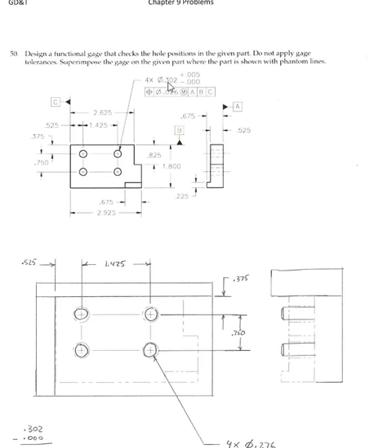So we've got 4 times 0.302 plus 5 minus nothing. Therefore, this 302 is the MMC of that hole. Then we have a 26 thousandths positional tolerance at MMC. Since we have an MMC in this tolerance, we can use a functional gauge to check these features.